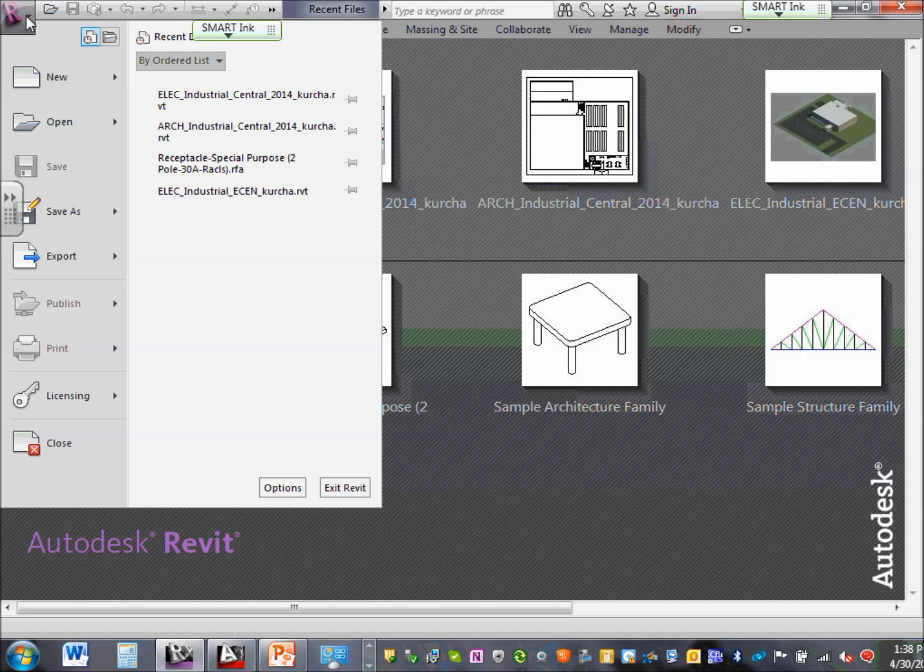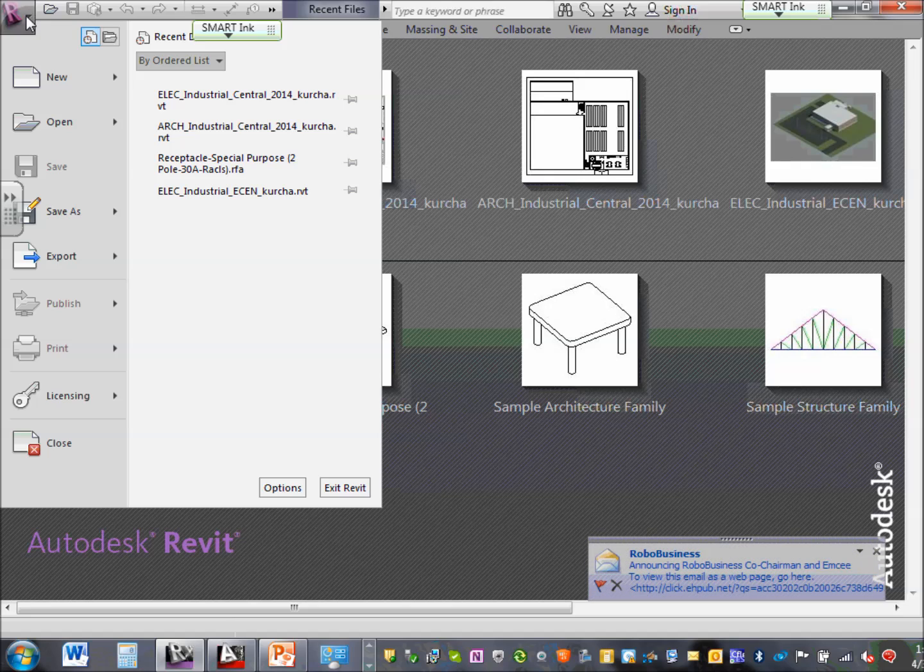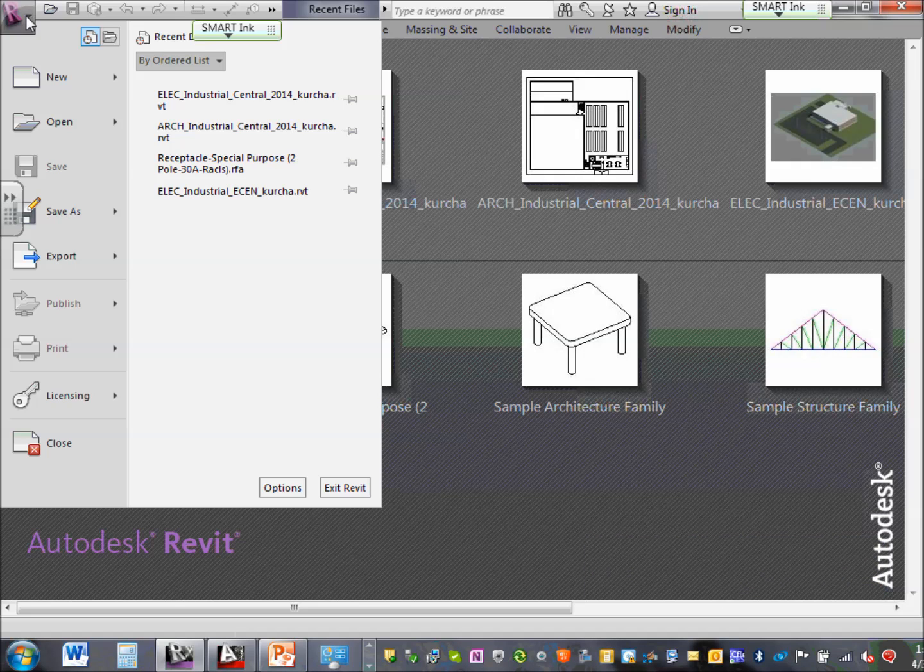Jeez. For Revit, guys, so you understand, when you work with Revit, there are two models. Or there's one model, actually. The architectural model. That will be given to you by the architects. That's what I gave you. Your job is not to work in the model. You don't work in the model because we typically don't get it. You have no control over it. You link to the model.